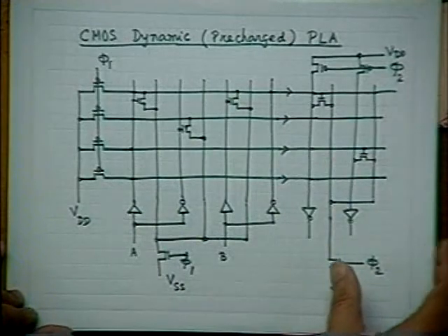But remember, this is not a static logic. This is a dynamic logic. And it does not matter. In most applications, static and dynamic logic are not at all important. Do you really use any logic at, say, 1 Hz or 5 Hz or 10 Hz? Rather, we go for higher megahertz, even now gigahertz, gigabits per second kind of things. So dynamic is the concept of today, and not static logic. But in memory applications, there is still importance.